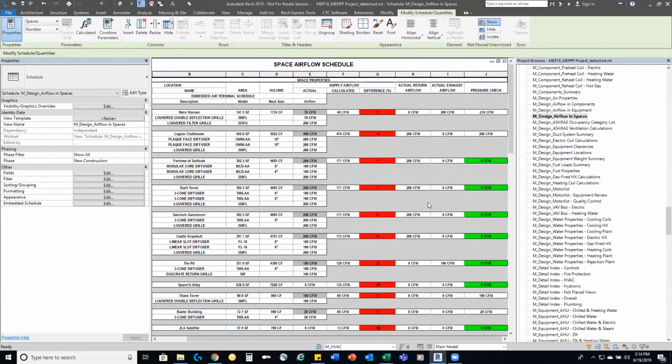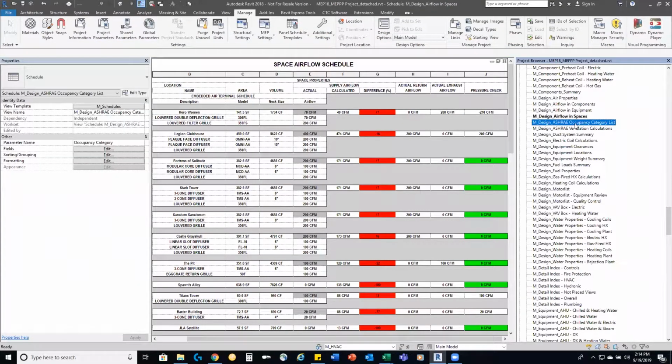One of my favorites, however, is Ashrae. We figured out a way to put Ashrae 62.1 calcs in Revit, but unlike what Autodesk has done with it, I like our method a little bit better because it gives you a more full range of control, and it also gives you the ability to edit a lot of the base data that's there. So as 62.1 changes and grows, as there's always amendments to our standards, this can move and grow with you with just a little bit of work.